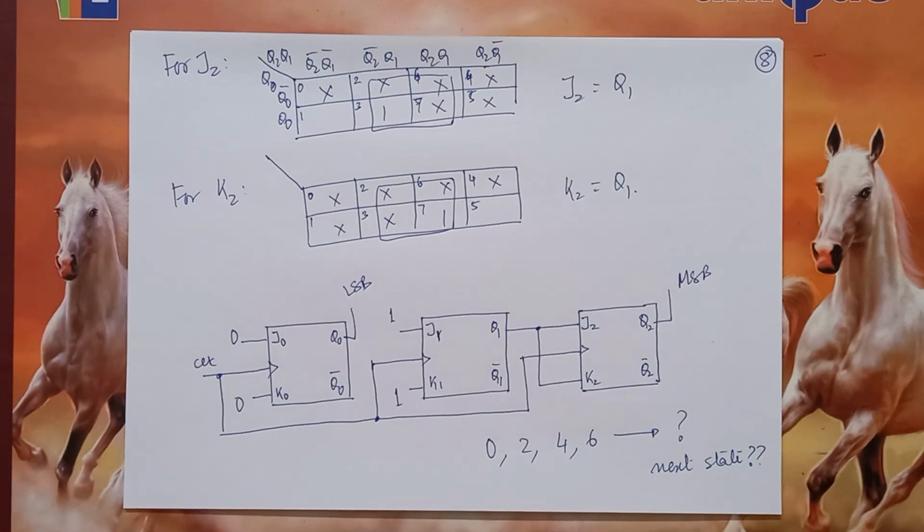So in this particular lecture, we saw how to design synchronous counters or synchronous circuits for different kinds of counting. We saw that we can generate any count using any flip-flop in the synchronous technique. In particular, we saw a mod 6 counter and we saw a 3-bit up counter for odd numbers.